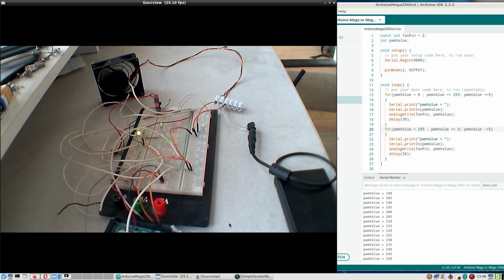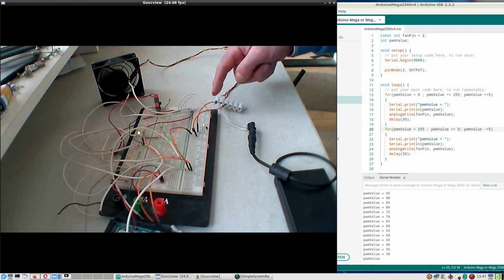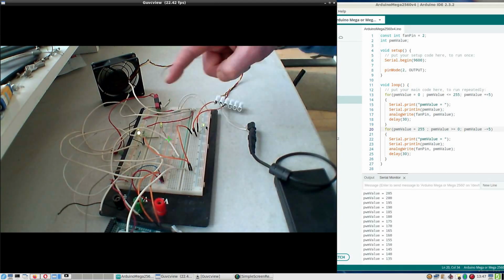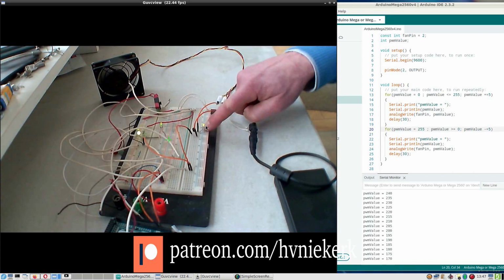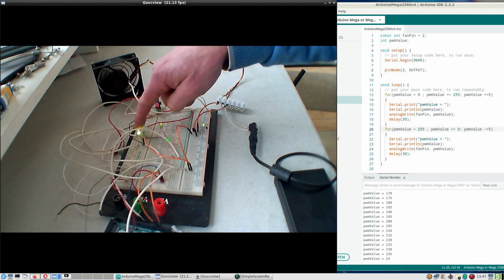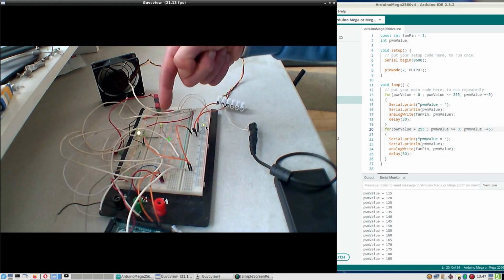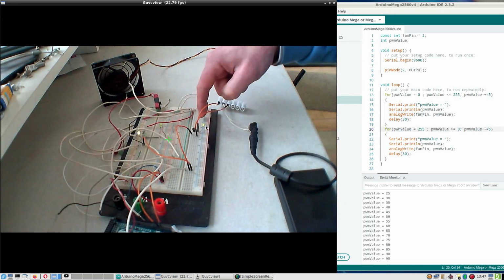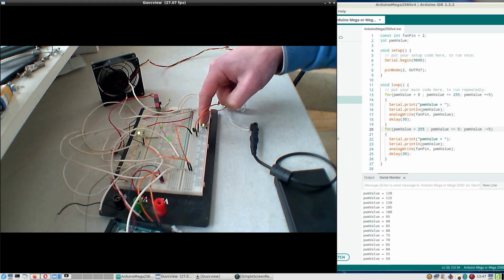And this is a different view with a webcam, and you can see, if you remember last time, that I have put here an LED, and that immediately shows one problem, which is that the wire from the pulse modulation to here is doing nothing. Here the signal is nice, going dimming slowly and then turning to on. This LED shows that this signal after the transistor is absolutely staying on, does nothing.